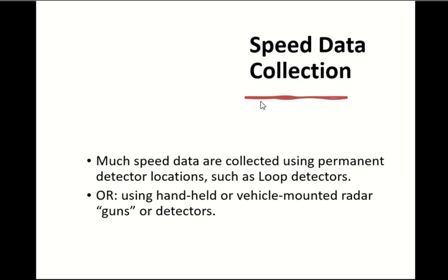So we know we can collect data using manual, semi-automated or automated techniques. If you are using a stopwatch, then it is manual. If you are using a radar where you have to press the button every time there is a car, it is manual. If you have a radar that takes the data by itself when the car crosses, it is semi-automated. If you put a detector which can record and transmit the data at the same time, and you don't have to take it with you, it is fully automated. So it can be any of these things.